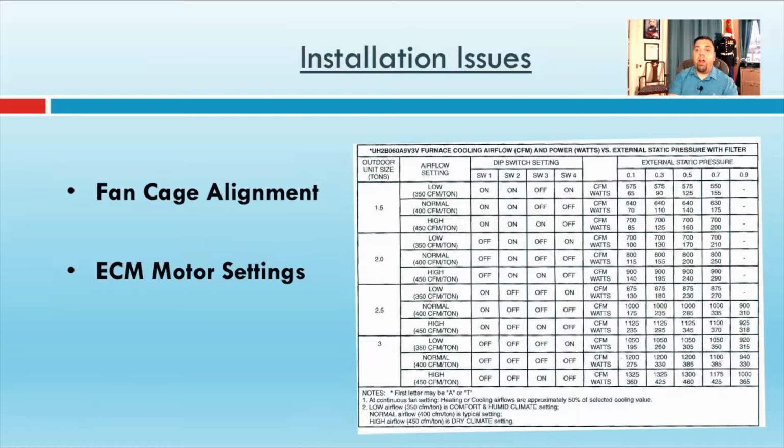So verify that before you start walking through, and you're going to notice it with static pressure. Typically, if you have a larger drive than what you need for your coils, static pressures are going to be through the roof before that coil, because it's going to be building up all that pressure. You're trying to move too much volume of air through this restriction, because the coil is smaller than what it's designed for the air moving through it. All right, so really important there.